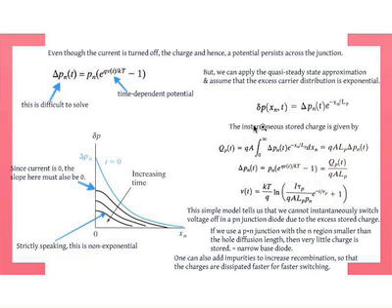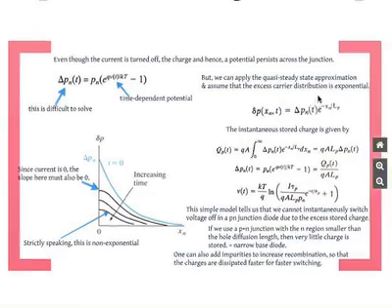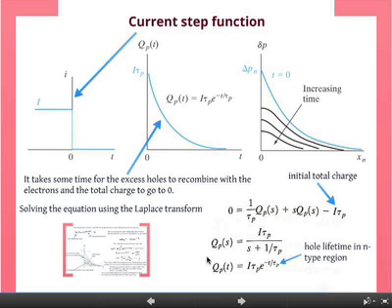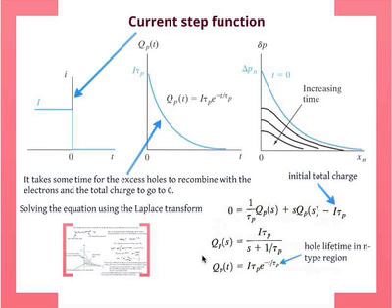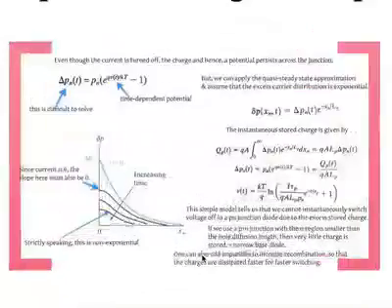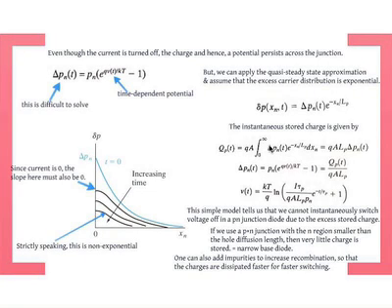But of course, we can also plug it into this solution that we found, because then we can relate it to the lifetime and to the current, because remember we're trying to get voltage-current relationships. So if we do that, you plug that in, do the integral over xn. This is an exponential, so it's pretty simple to do the integral. You get something like that. Now, of course, if you look at this, that's just the total excess carriers at xn equals 0 at the interface. And you have these terms here.